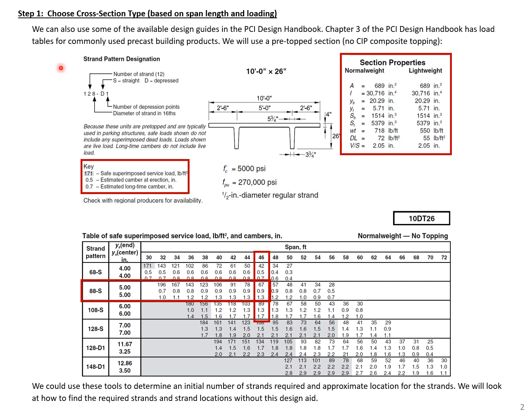The top of this design chart has some information on our section: the top flange width we'll need, the total depth, and the thickness of our top flange. Then we have some standard section properties for this 10DT26 section. You can see we have our gross section properties, the weight, and our volume to surface area ratio, which we'll need for our creep and shrinkage equations.